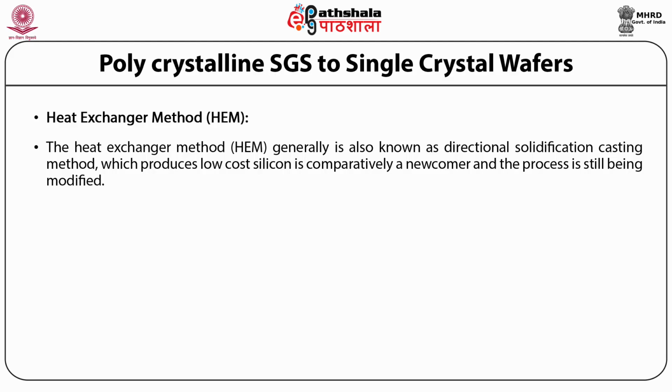A single silicon crystal seed is used for the crystal growth at the bottom of the crucible. Control heat transfer arrangement is made to avoid the melting of crystal seed, and a graded silica crucible is used to avoid the heterogeneous nucleation at the crucible walls.